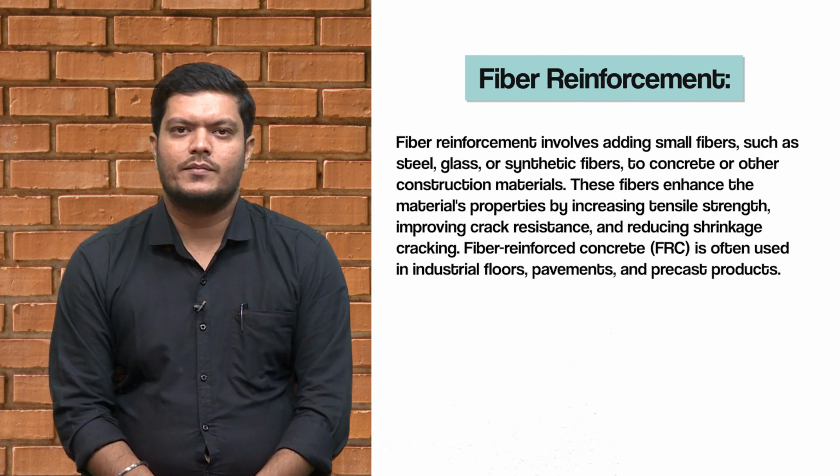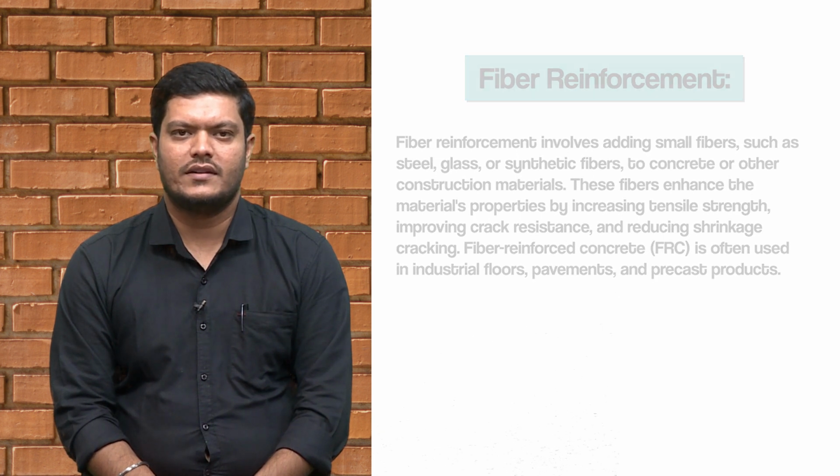Second, fiber reinforcement. Fiber reinforcement involves adding small fibers such as steel, glass, or synthetic fibers to concrete or other construction materials. These fibers enhance the material's properties by increasing tensile strength, improving crack resistance, and reducing shrinkage cracking. Fiber reinforced concrete (FRC) is often used in industrial floors, pavements, and precast products.